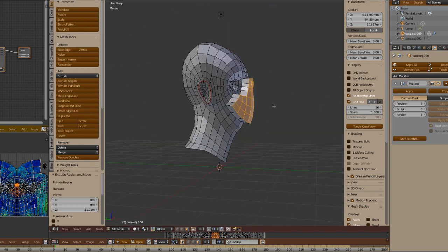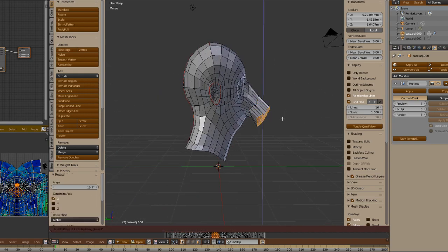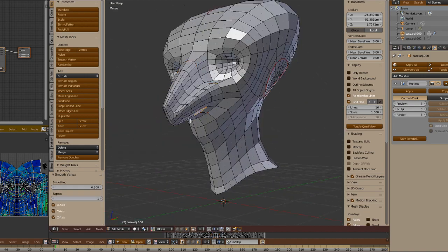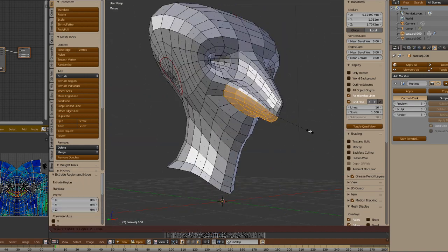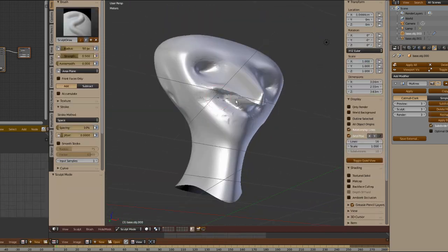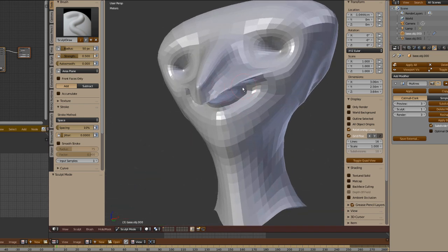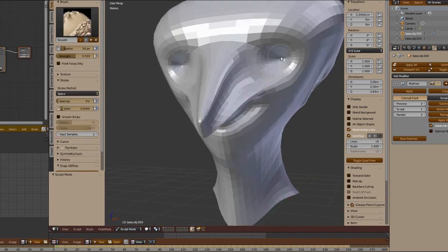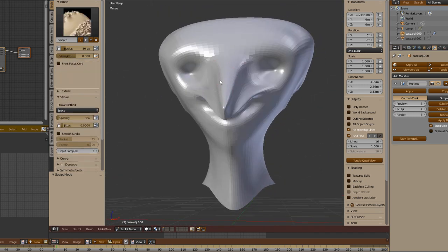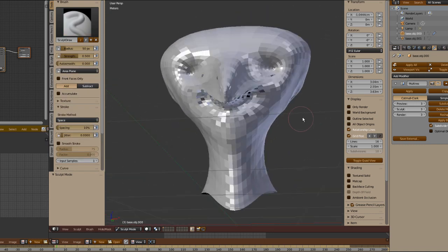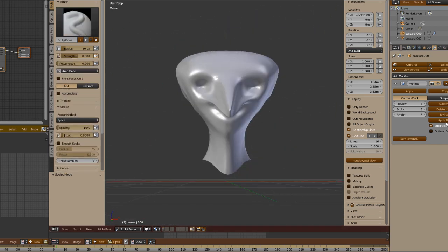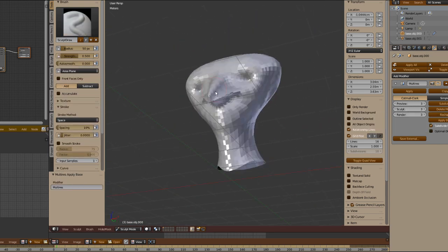Another interesting thing is that the user does not need to get stuck in the same mesh topology. This means that at any time you can insert and modify the mesh topology, and you can create new geometries using the extrude tool, which will not break the operation of the multi-resolution modifier, as you can see. You may think that seeing this result the mesh is all broken and full of problems. I thought so, but not really. The mesh shows only a few minor flaws that I just softened in the area at each level of subdivision and everything is solved and smooth. That's fantastic. Just good things, don't you think?